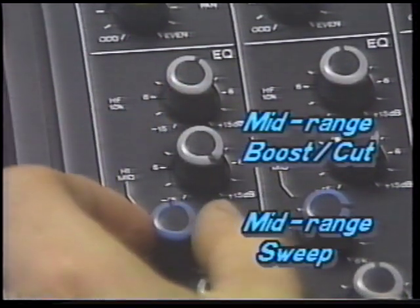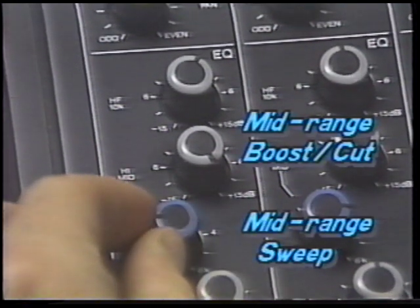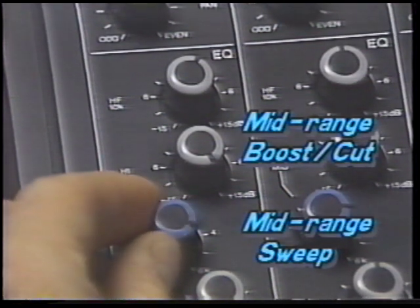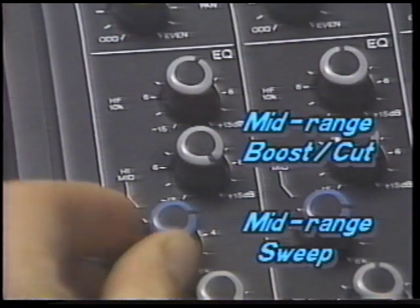Many times, the best way to find the frequency area that you're looking for is to turn the boost control up full and sweep it through its range of frequencies until you find the frequency that seems to be the most pleasing to you, or those you want to diminish. Then set the boost or cut to the desired amount.